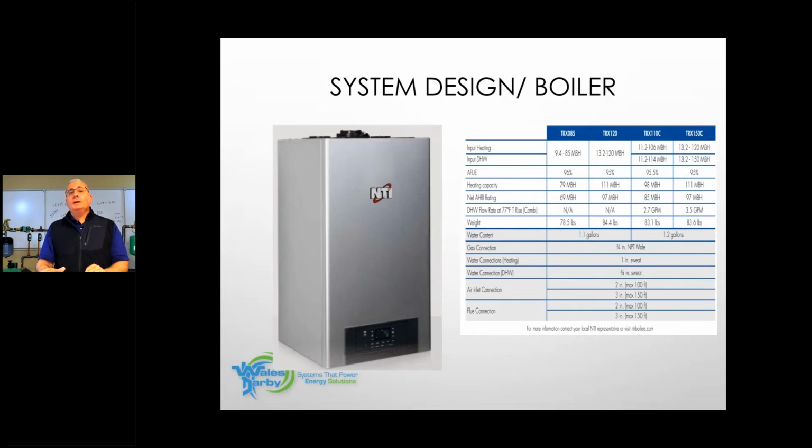One thing you have to be very aware of with combi boilers, especially in this territory, is that our water quality, pardon me, is not good. All right. You want to have a filter system in front of that to protect that heat exchanger from very hard water. We happen to represent A.O. Smith. We have a product, the Preserver filter, that if you're doing anybody's combi in this territory, I highly recommend you put in front of the boiler to protect the domestic side and keep that heat exchanger clean.